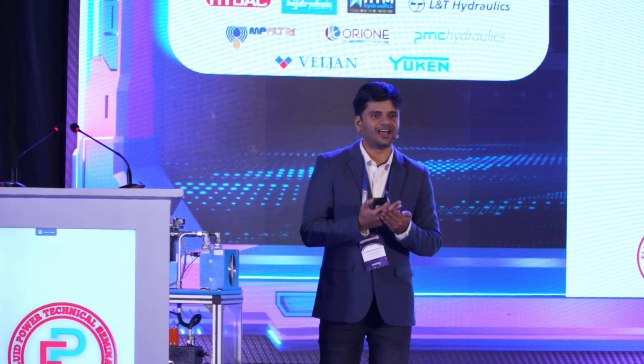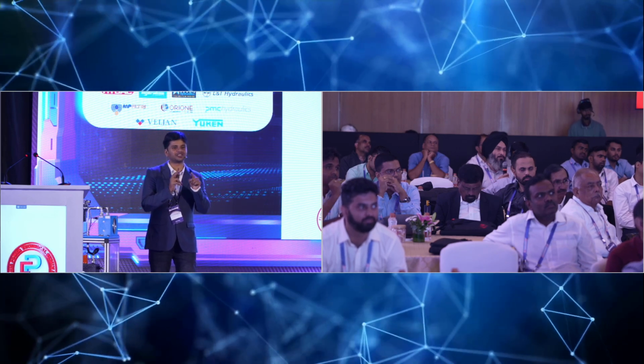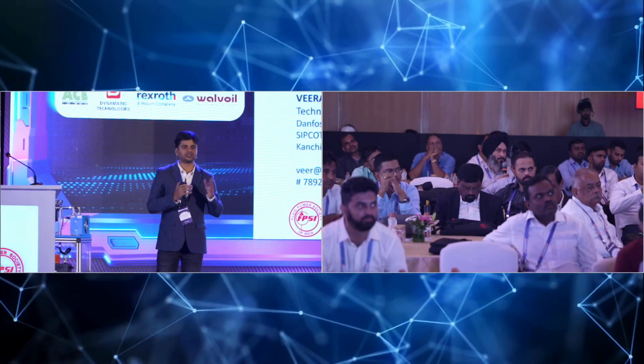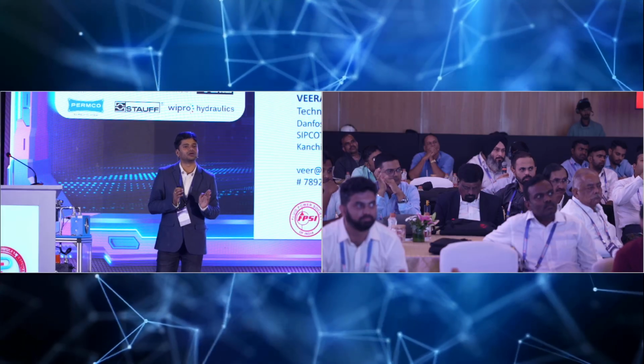We try to have a super duplex material, and the clearances, I don't want to disclose what kind of clearances we have between the valve plate and the port plate, and between the cylinder and the bushing. That is Danfoss property. But you're right that one of the important things is the clearances, how we manage them, and the timing, how intelligently you connect the high pressure side to the low pressure side. And what kind of corrosion resistant material you are using to have a good life, because seawater is very corrosive, and it can damage the entire pump in a very short time.